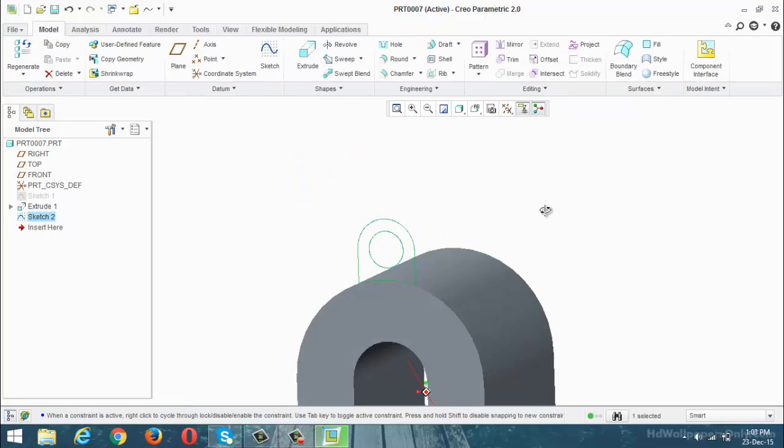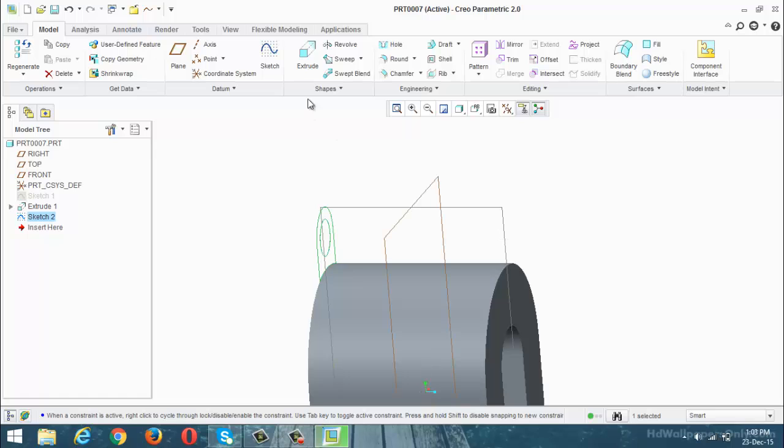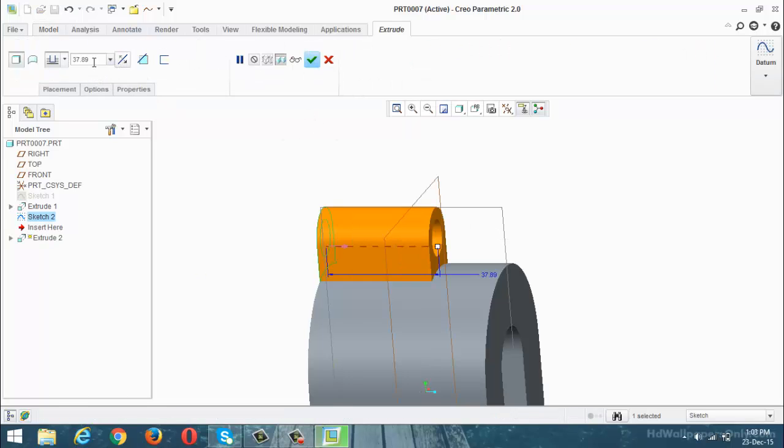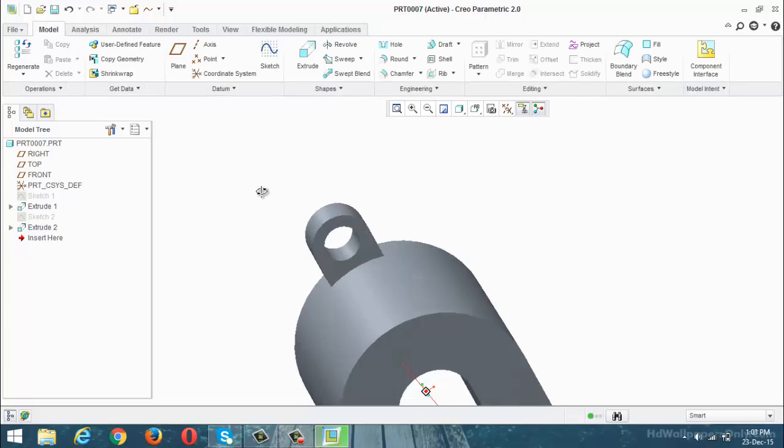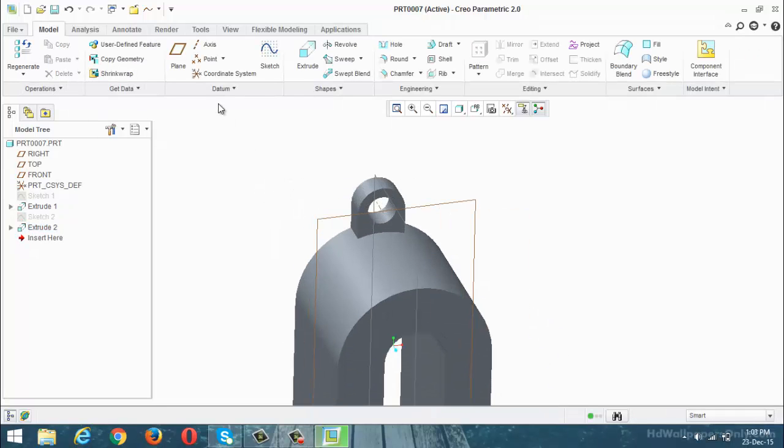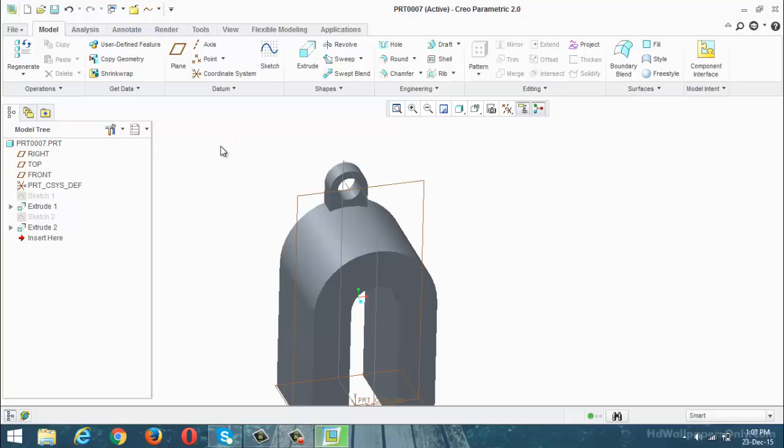Again how much extrude? Extrude 10. Now extrude to reverse direction, value 10. Just okay. Then again next, you can design which one? Now I am going to design one rectangle. Again apply the remove material. How much material remove? 4. Again see here, 4 value.